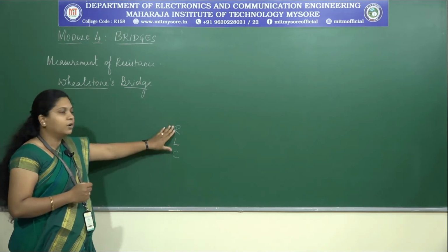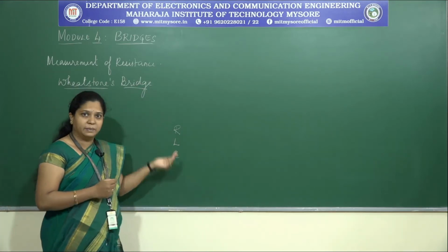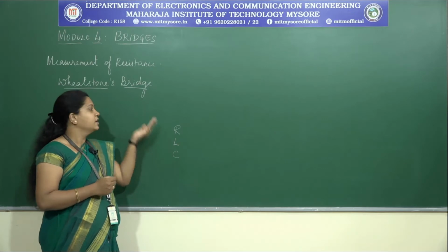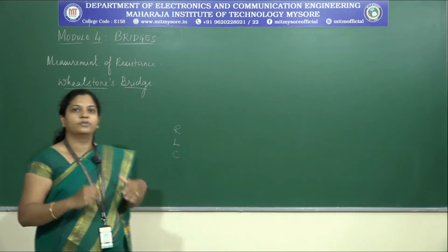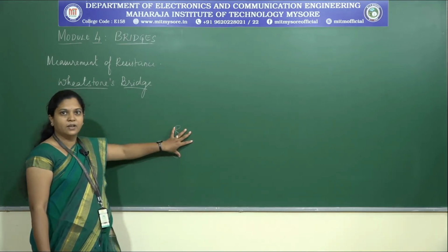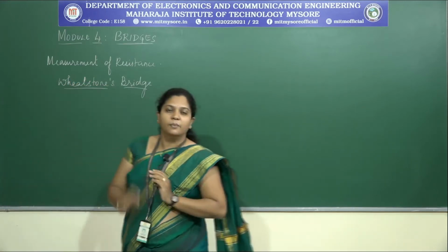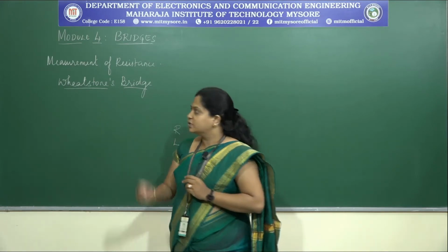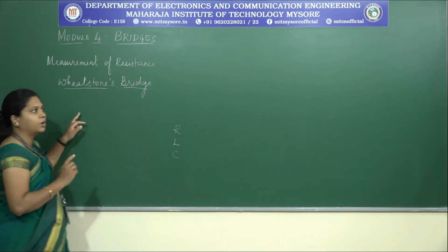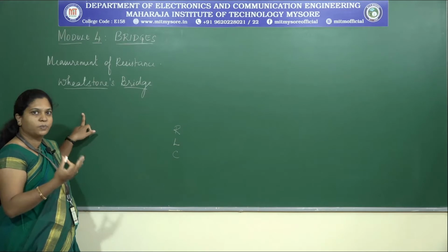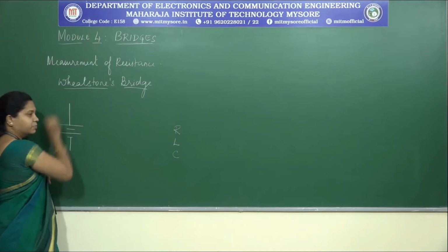Out of the instruments we have studied so far, voltmeters, multimeters, frequency meters, time measurements, these bridges are specifically used to determine the value of the unknown load elements, starting with the resistors. For the measurement of resistance, the widely used bridge is the Wheatstone Bridge. Let me draw the figure for a DC Wheatstone Bridge, where we make use of a DC supply as the input.